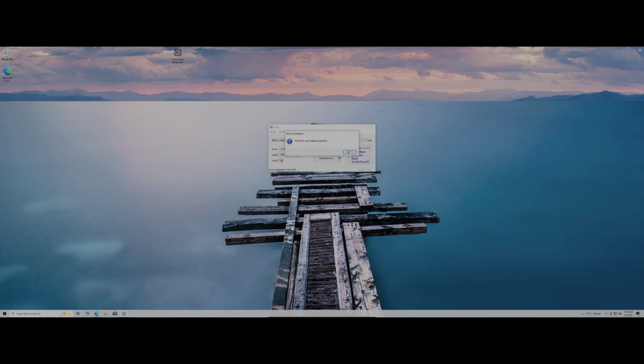All right, once the driver is installed, we can hit close. We make sure that now interface 0 has that Win driver in the actual driver slot rather than this slot over here, and we make sure this says reinstall. So now that we know the driver is installed, we can get rid of that.